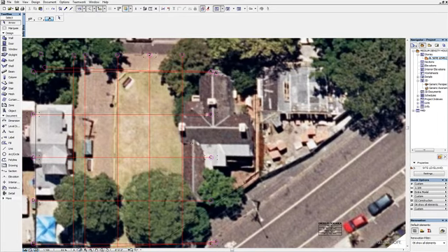Okay, we'll be able to tell a bit more clearly where this particular roof lies in relation to this multi-plane roof by a photo of this side elevation. Okay, so the left side elevation of this building. But in the first instance, what we'd like to do is create this roof as a multi-plane roof, create this roof as two single plane roofs mirrored about this ridge line.